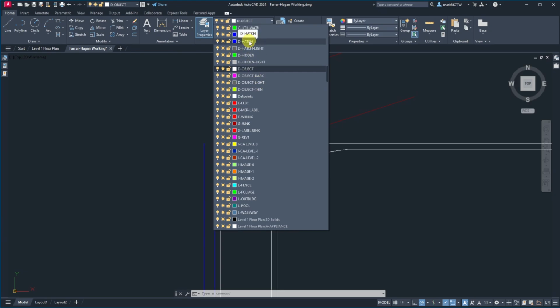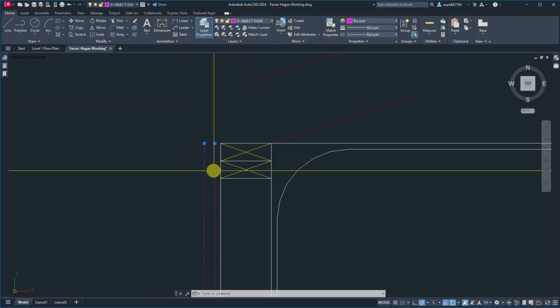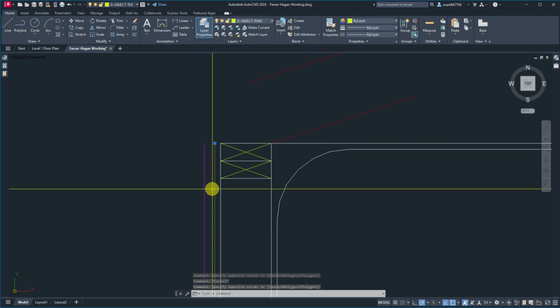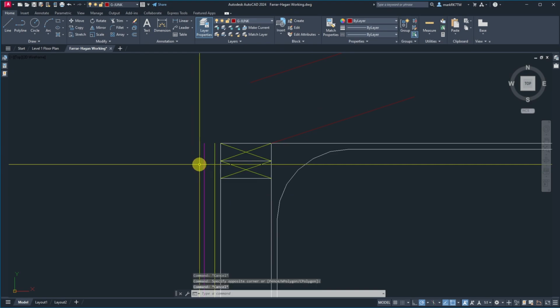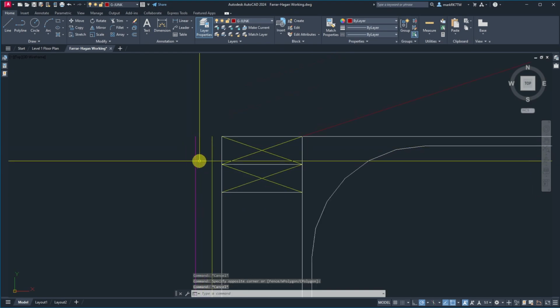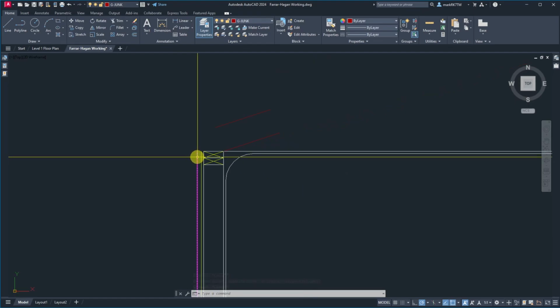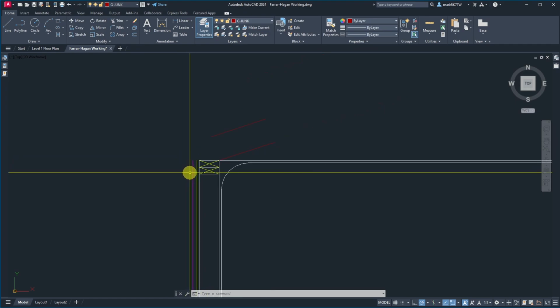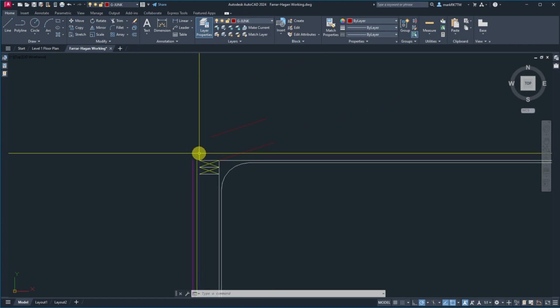This is a thinner line. This is 0.0039 inch. This is 0.079, something like that. So pretty thin line. So I'm going to make this dark for now, and then I'm going to make this one in between thin, because when I plot, if there's lines too close to each other, it just turns into a big messy blur. This is my outer layer. And my outside line is always my dark line because you outline your building in a dark, heavy line.